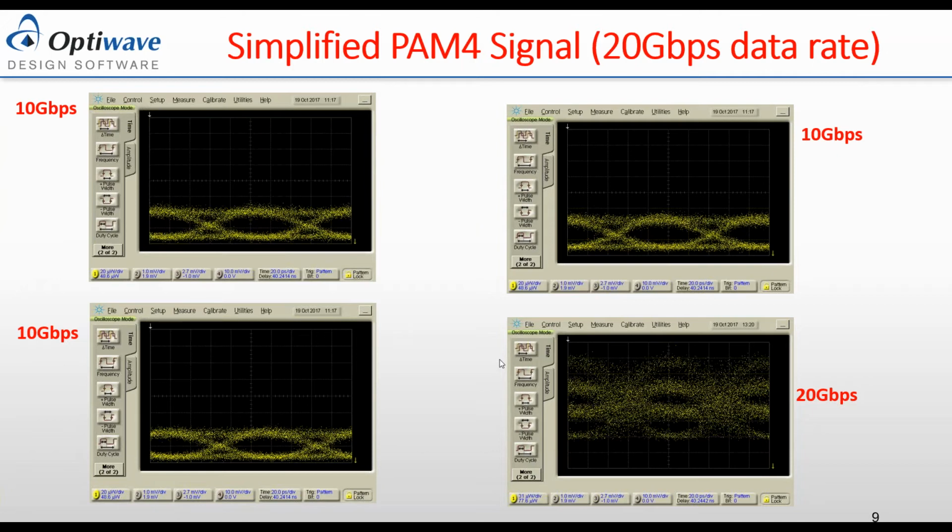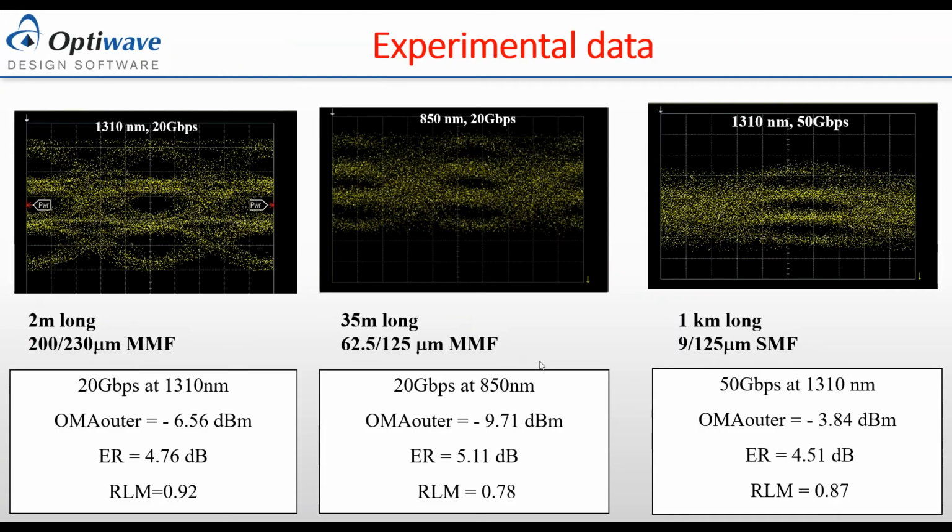So what we have effectively proven here, as I was mentioning earlier, is that these two bits, MSB and LSB, could be driven independently of each other, and then they are combined inside the fiber. They do not interfere, only their intensities are added at the photodetector, and with that we have the PAM4 signaling scheme available to us. This was the result at 10 gigabit. Let's go to our next slide and we will be able to see higher data rates as well.